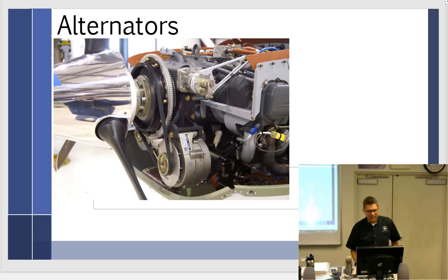And let me tell you something. That prop is not fun to change, because those bolts right there are really hard to get to torque. You need an adapter. You've got to fight it. And the safety wire, there's no safety wire there. The safety wire to do that will take you some time. It is one of the worst safety wire jobs in general aviation right there.